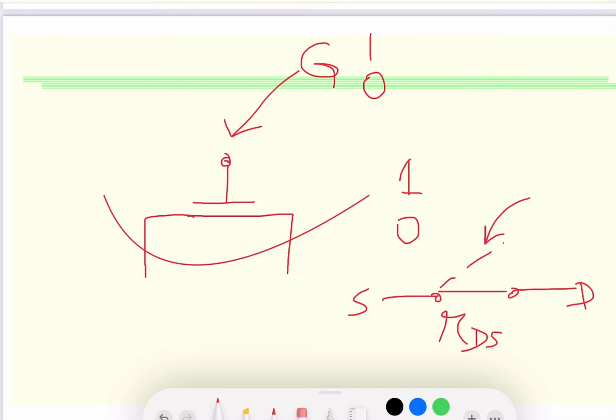Then we took it further, looking at how we can make the drain to source voltage higher than the overdrive voltage to get to saturation. But here we are just using it as a switch, which means that when the gate voltage is high, the power supply level, whatever has been applied, would go through, and we will get a high voltage on the other end.